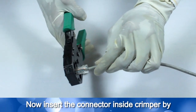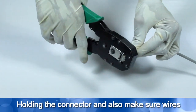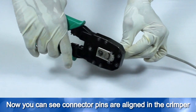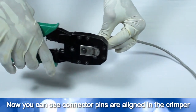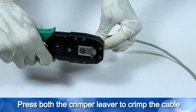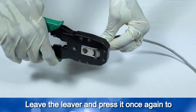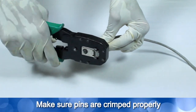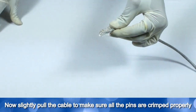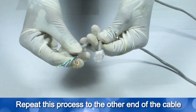Now insert the connector inside the crimper by holding the connector, and make sure the wires do not come out from the connector pin. Now you can see the connector pins are aligned in the crimper. Press both the crimper levers to crimp the cable. Leave the lever and press it once again to make sure the pins are crimped properly. Now slightly pull the cable to make sure all the pins are crimped properly. Repeat this process on the other end of the cable.